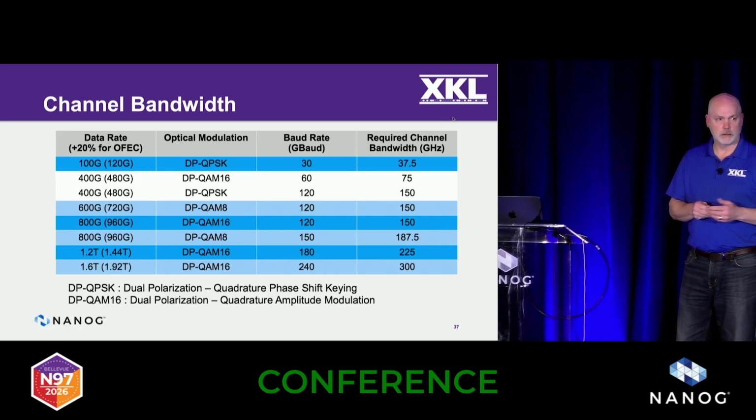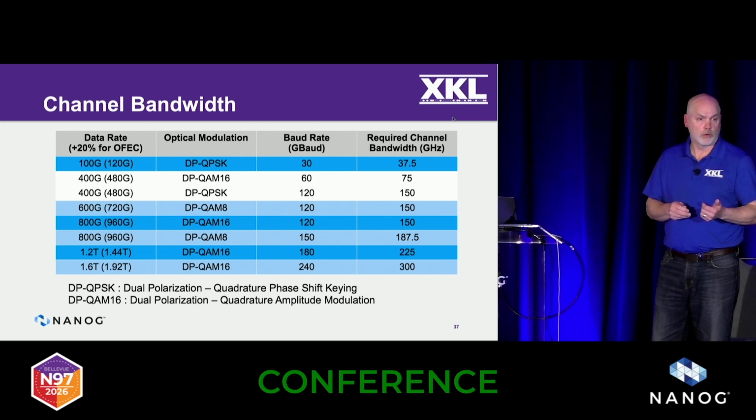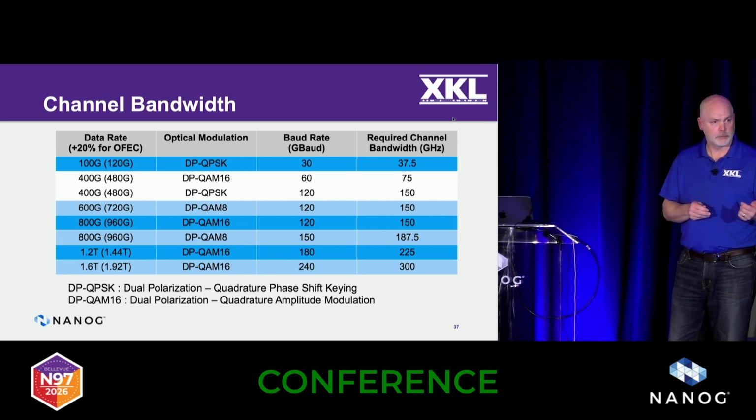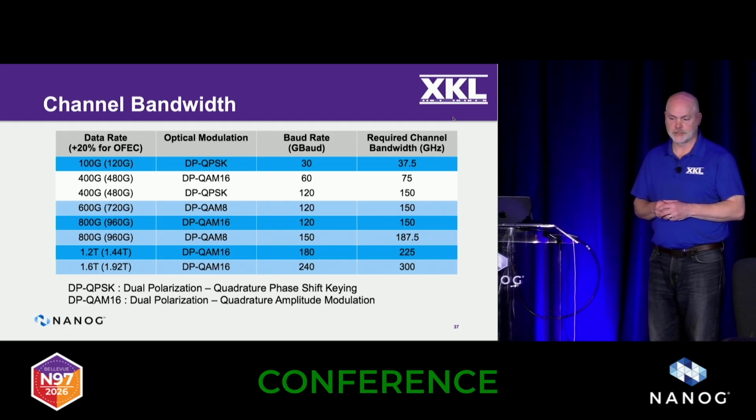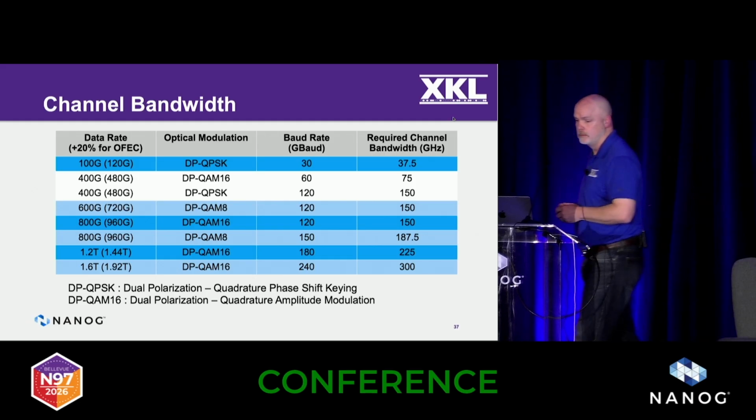So that's really simple math. So you can get more or less efficiency out of your fiber utilization, but the important characteristic here is about the reach. A QPSK signal is going to go much, much further than a QAM 16. We're going to talk about why that is.